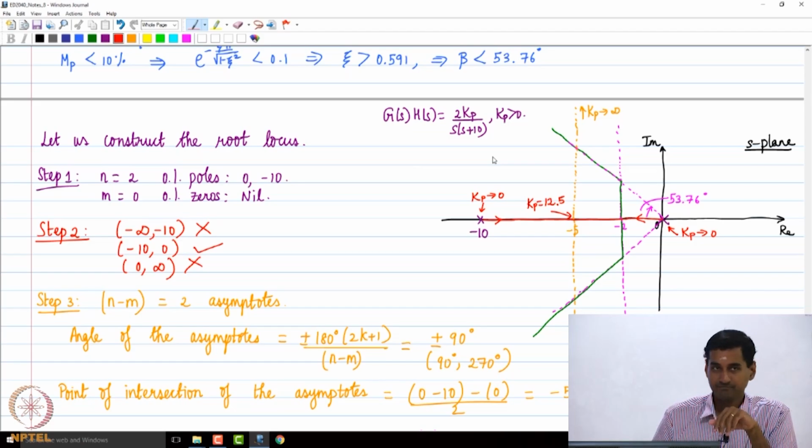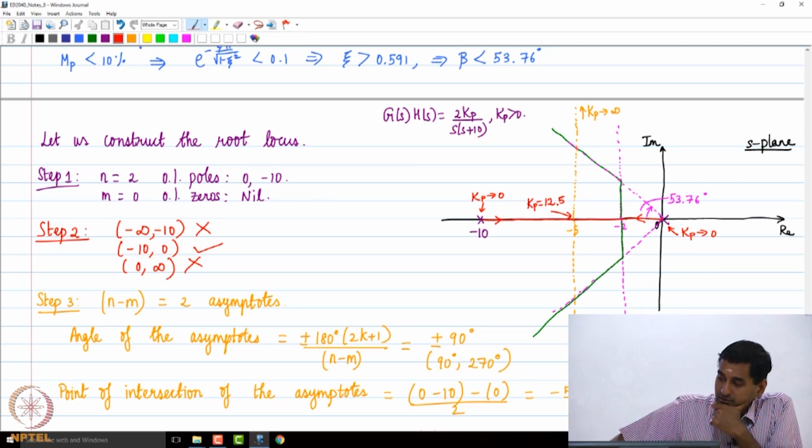Okay, yeah. The value of s_b can be complex. You mean the breakaway point? Yes. If you have a breakaway point in the complex plane, you still need to check the value of k. If k is positive, then it's a potential breakaway point or break-in point.